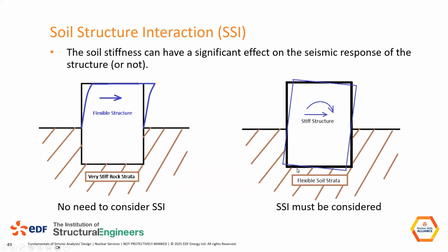However, for a more realistic case, there'll be some flexibility associated with the soil, and the structure will have a reasonable stiffness. And there may also be a response where the structure is actually moving with the soil. So the structure is essentially rigid and it's moving with the soil around it. In this case, the response of the structure is actually governed by the soil, and you need to consider that in your analysis. You cannot analyze the structure on its own. You need to have some representation of the soil, whether that's modeling the soil itself or representing the soil with springs, which can be frequency dependent or independent.